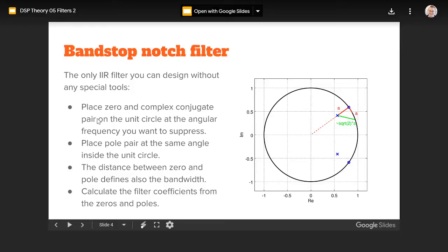Easy! Magic! So what we need to do is to first find what our corresponding frequency is in this relative frequency, omega n, and then just decide what our half width of the filter is and use that as the radius for the pole.